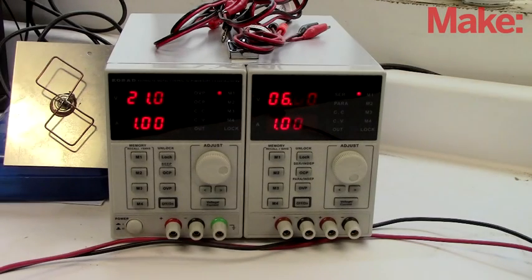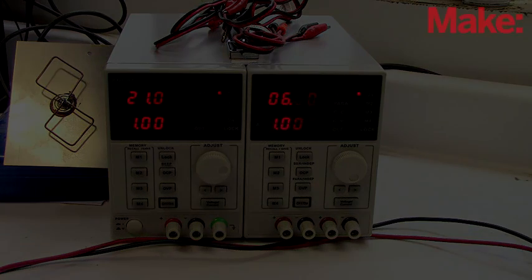This is my lab power supply. It has 2 channels that are variable and 1 channel that is set to 5 volts only. A good output current is required. I like 3 amps. Both my channels here have 3 amps of output, and again they're variable from 0 to 30 volts. So a nice good solid benchtop power supply is a key need in my lab.